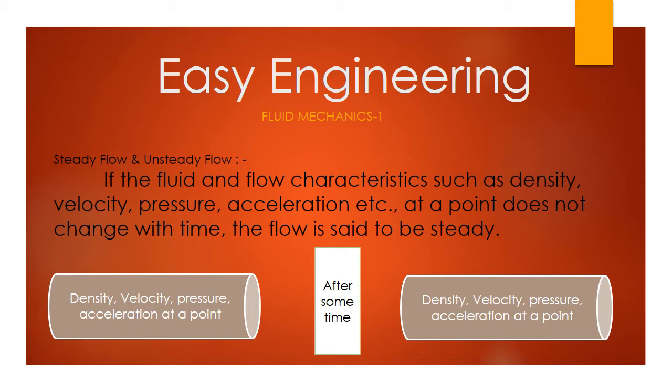So what is steady flow? If the fluid and flow characteristics such as density, velocity, pressure, acceleration, etc. at a point do not change with time, then the flow is said to be steady flow.